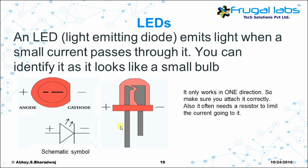A LED will have two legs. The longer leg will always be positive and the shorter leg will always be negative. Where the shorter leg is present, you can see that there's a flat surface on the LED itself, and this is the schematic symbol. Please note that the LED will work in only one direction, so if you do the connection wrongly, you might end up burning it.